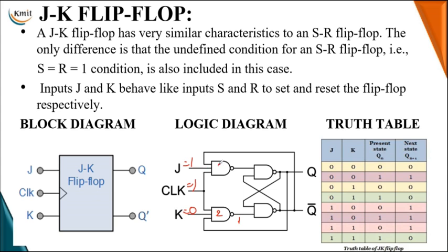But in order to obtain the first NAND gate output, I have to check my present state. Now present state is 0, so the complementary state becomes 1. That complementary state is applied as your input. Hence, if all three inputs are 1, the first NAND gate output will generate a 0 output. Now if any input of your NAND gate is 0, this third NAND gate output will shift your present state to logical 1. So 1 1, which will be turned into your 0 state.